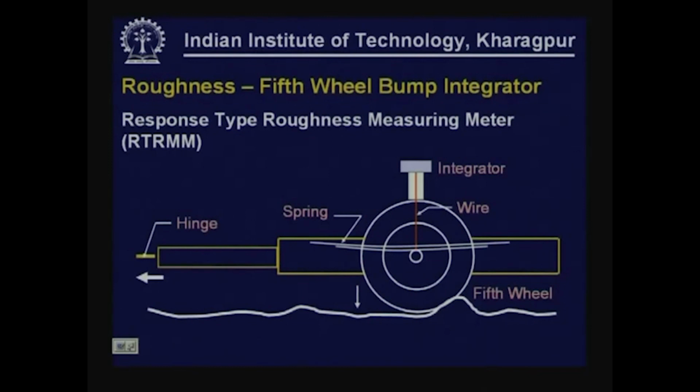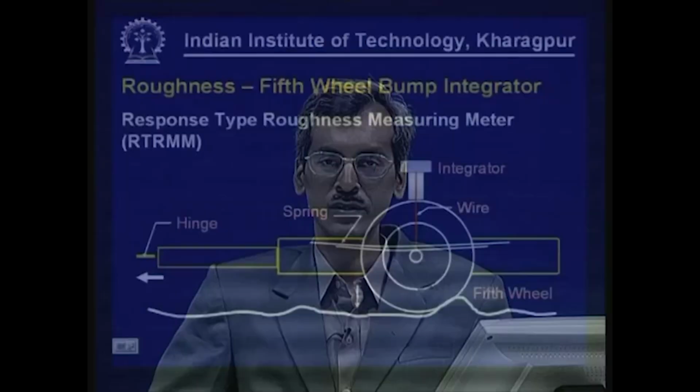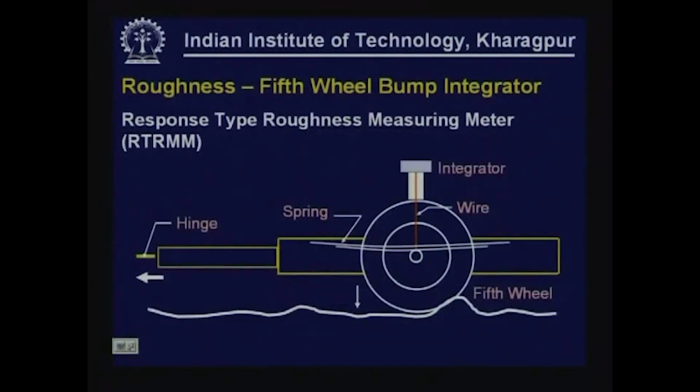The roughness of the road can be obtained in terms of the surface profile. One can measure the surface profile by taking levels by rod and level procedure, or there are other equipments which give us indices that say something about the profile of the road. These indices also are expected to be giving some idea about the comfort that the road users get, but response